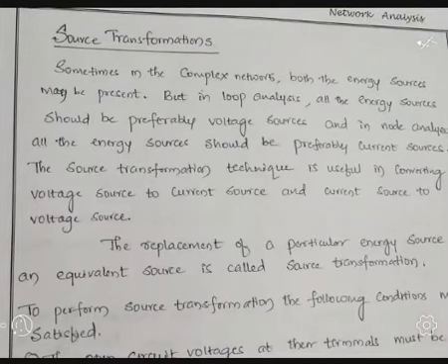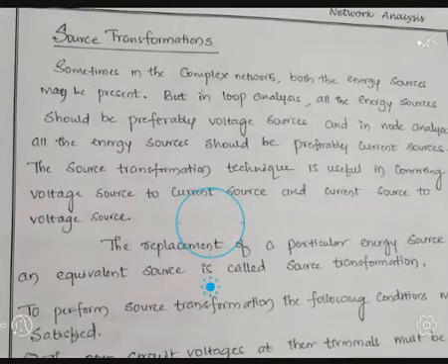But in loop analysis, all the energy sources should preferably be voltage sources, and in node analysis, all the energy sources should preferably be current sources. So the source transformation technique is useful in converting voltage source to current source and current source to voltage source.